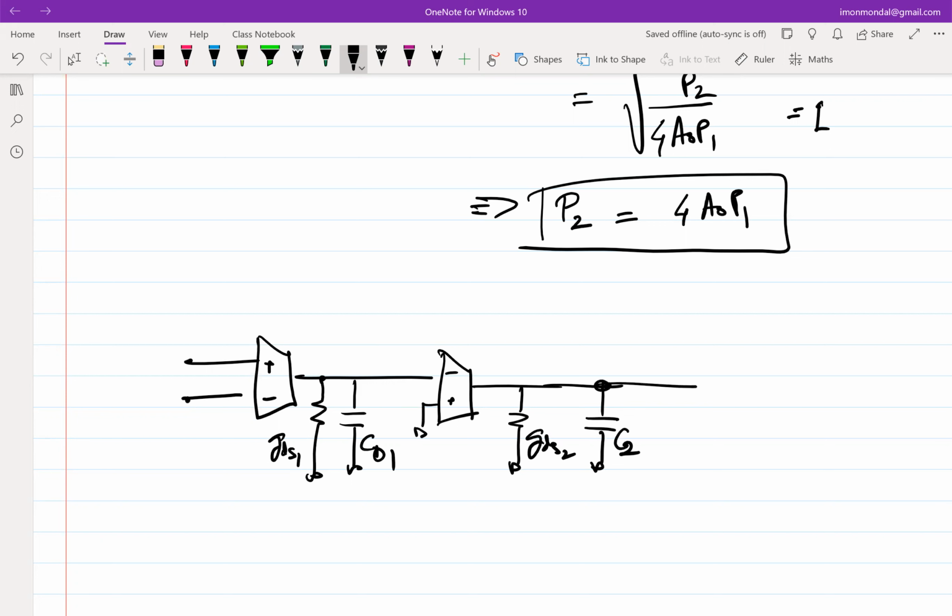So what is your strategy? The intrinsic capacitance cannot be changed, but in your PDK you have extra capacitances. It's difficult to remove capacitances, but it's always easy to add capacitance.